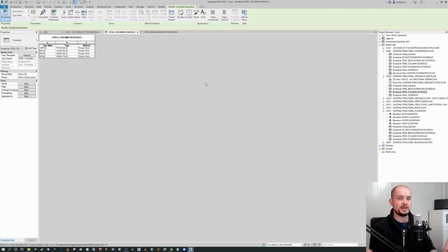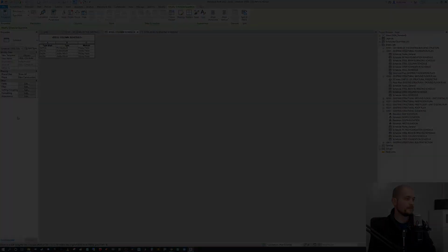It also just makes sure that the right people are controlling the right elements at all time, and you see if there's, let's say, cross-pollination between people within your organization or third parties who are editing things that they shouldn't be. So it's a very, very quick sanity check for a BIM coordinator or BIM manager to be able to go in and check the work set integrity within a model without actually having to manually go through the work sets. You can literally just pull up a schedule very quickly, add the work set parameter, and you're off to the races. So that is a very small but very substantial quality of life improvement for quite a few BIM users, I would say.